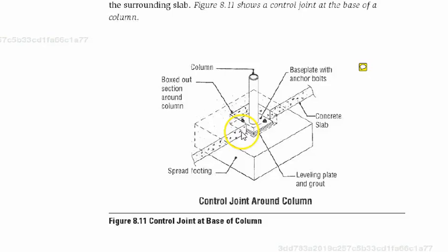There are natural places that concrete will crack, and that's why you see every 5 feet on a sidewalk there is a line, and those lines are control joints. You'll also see a fiber joint in there, generally, say every 100 feet or so, or every few joints will be a fiber joint, but the rest of those control joints are put in either with a saw or a tool.